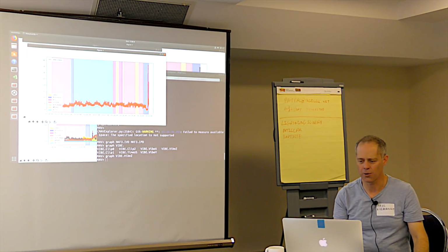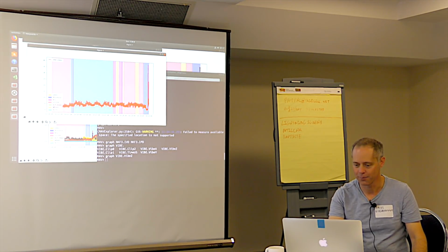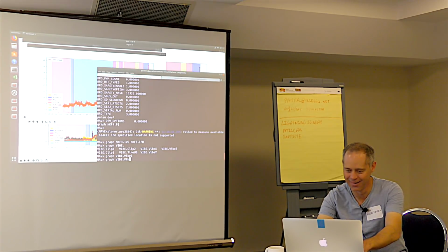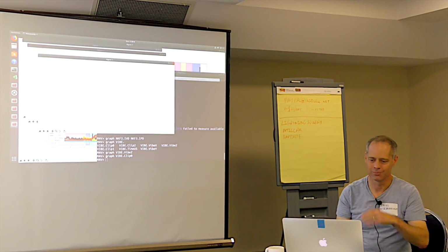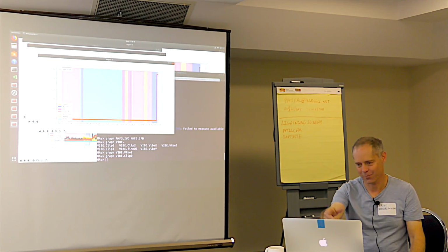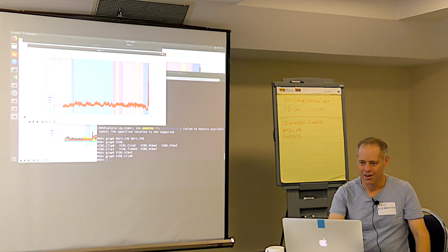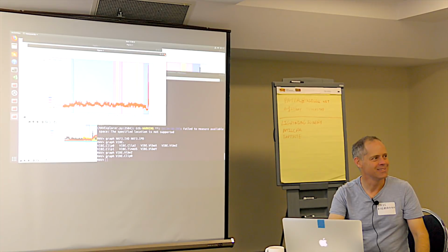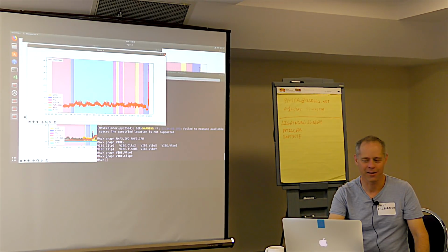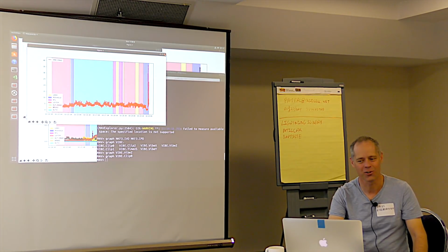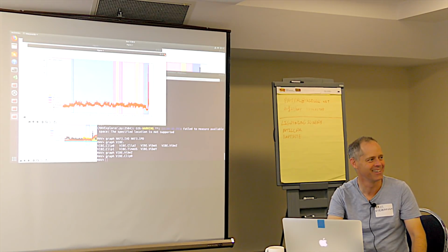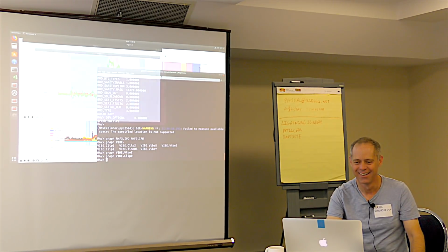The vibe levels look low, up to the point where it hits something. And then I can do clip. There's no evidence of clipping up to the point where it hits something. That's after you hit something, that's the mode you go into. Apparently, flying into an object, it tends to fire off the clip indicator. Crash and disarm.